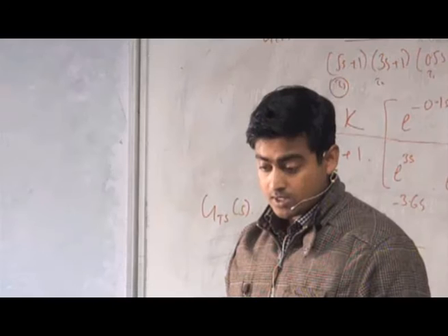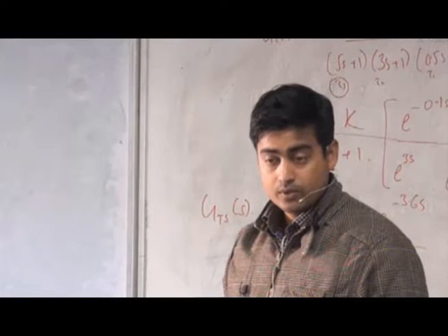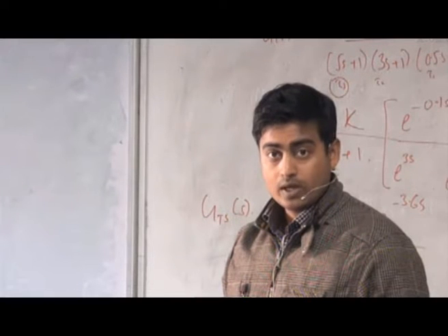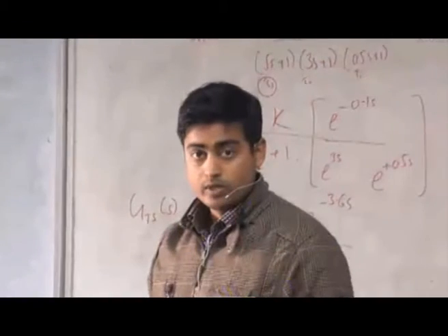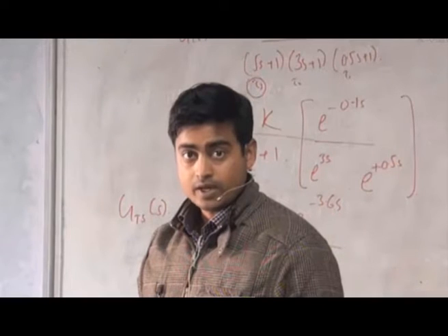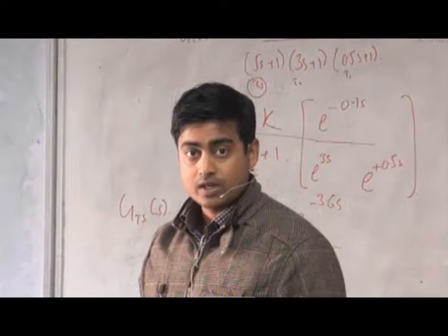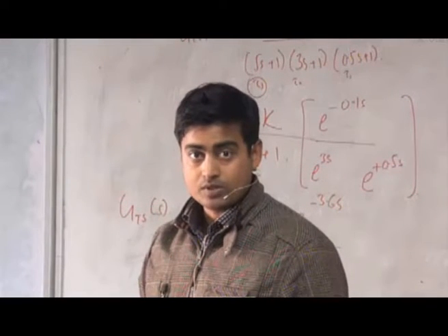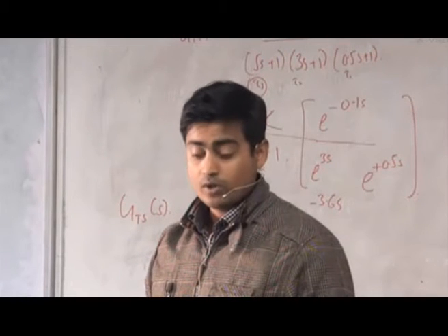What do you understand by the steady state gain? Because the steady state gain basically gives you what is going to happen when time t tends to infinity. Okay, it is an inherent property of the transfer function. Either you do the time domain analysis or the frequency domain analysis, the things are going to remain the same.